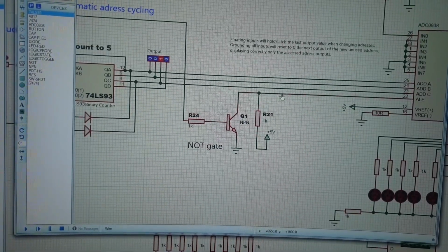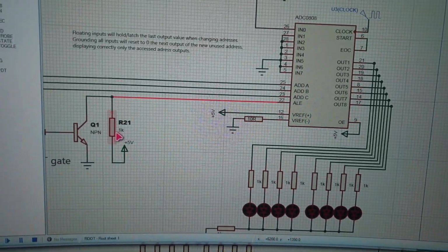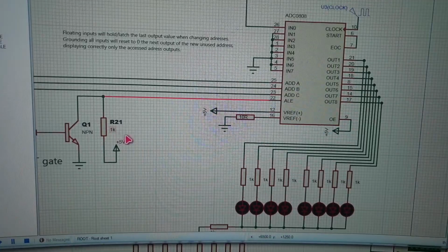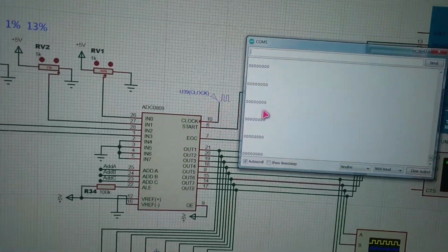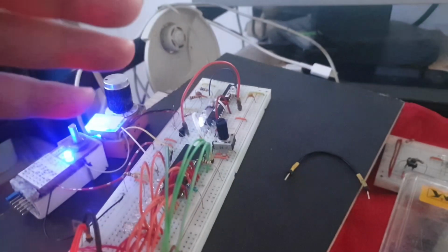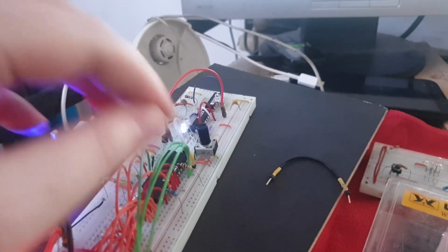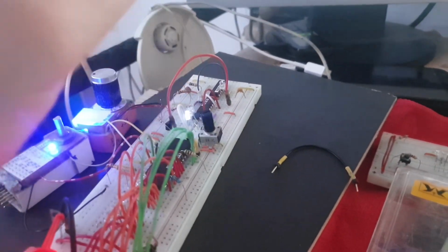So I was having this line, this ALIA line, connected to positive through that 1 kilo, and it's not good. It didn't work. It was giving me all the time 000 on the output here, like it's showing right now. It was giving me 000, and I started to unplug things until I managed to find that wire. What is that wire doing there? Let me take it out.